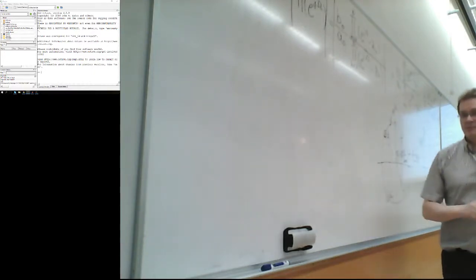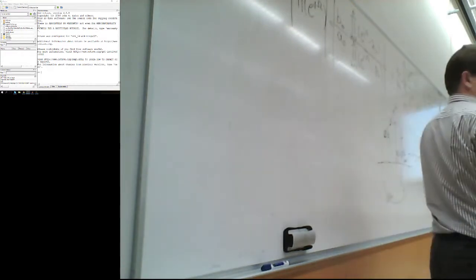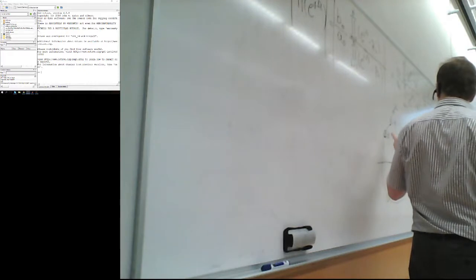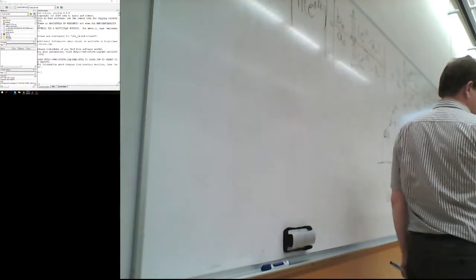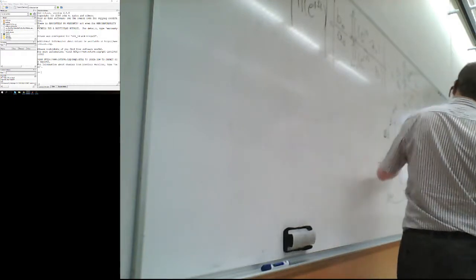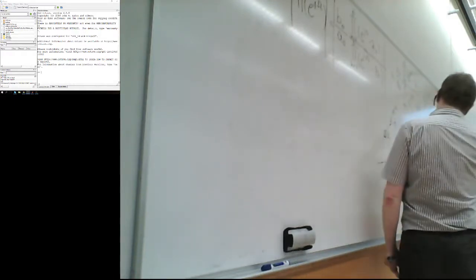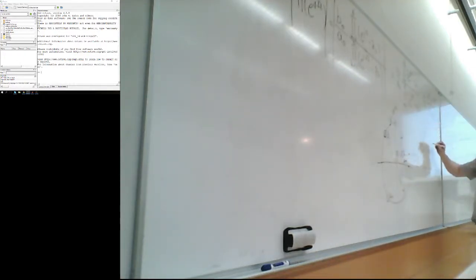So those special points there are the locations of zeros. Zeros in an IIR system are located on the unit circle to give the local minimum. You need suppression of some frequencies exactly at that point, and then these poles are located somewhere closer to the unit circle to add some gain. So that gain here is caused by the pole, and this one is the zero on the unit circle. Got it?